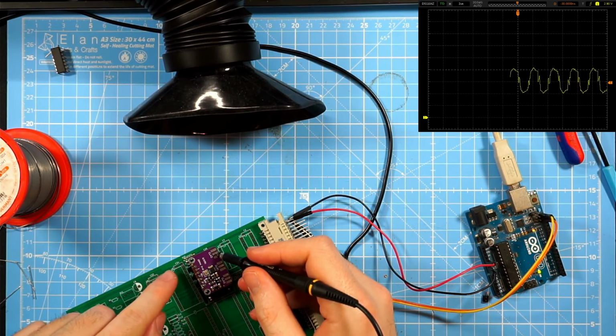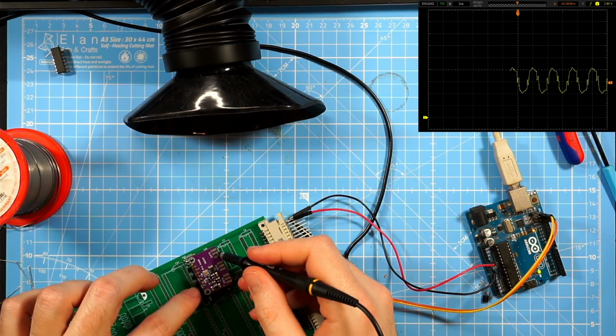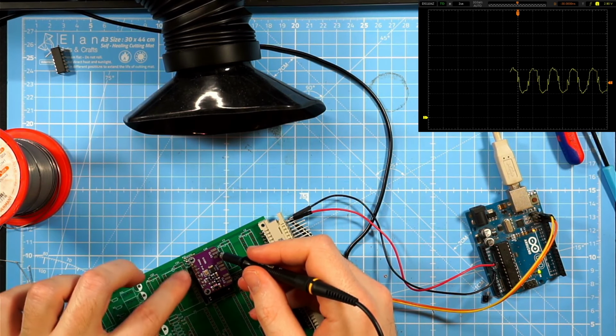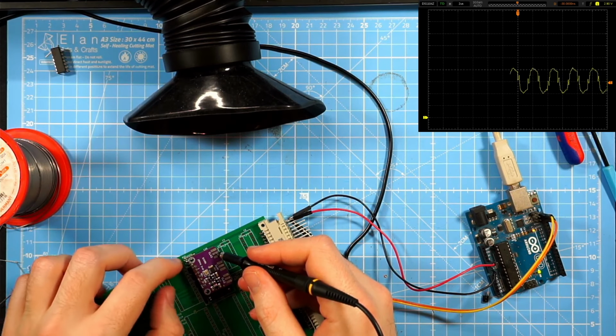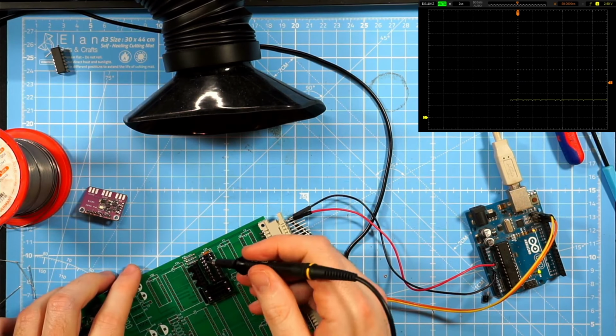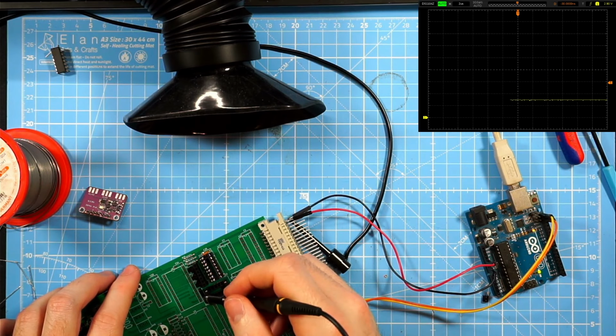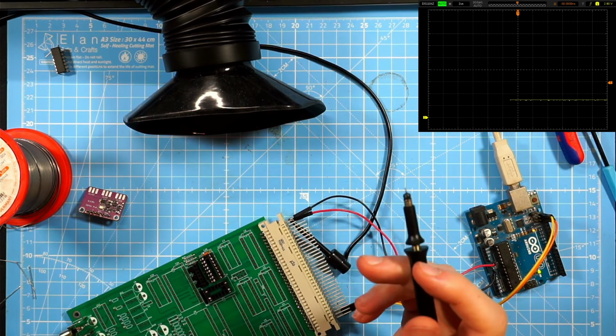For now I'll just unsolder those transistors, everything right here, and just connect patch wires directly from those resistors to this resistor network. I guess that's that.